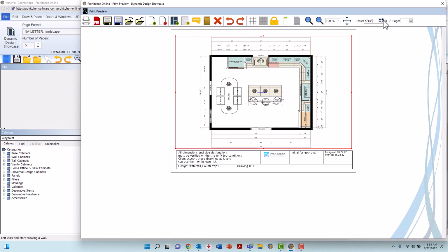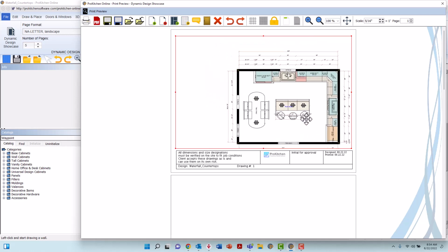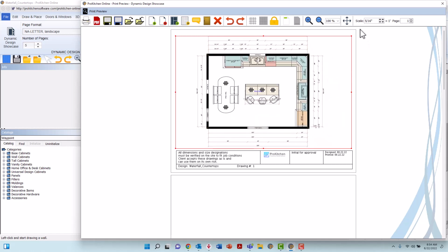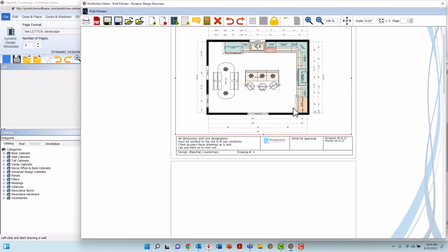If you want to relocate the view within the box, left-click the icon to the left of the Scale tool, turning the cursor into a grabber. Then left-click and hold the view to reposition, remembering to click the mover icon once more to return to mouse mode.